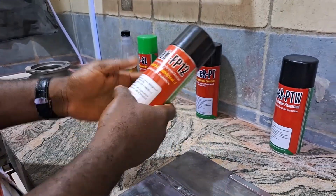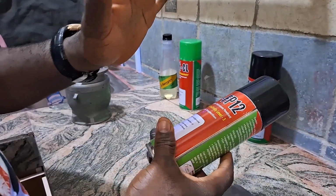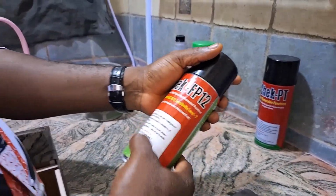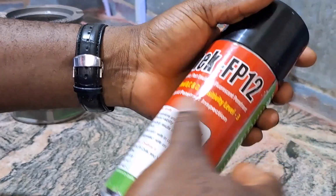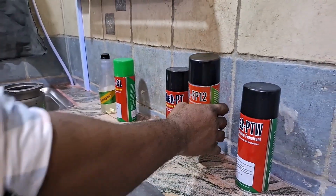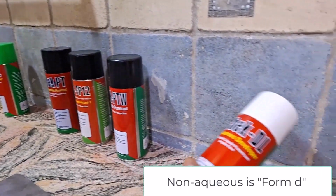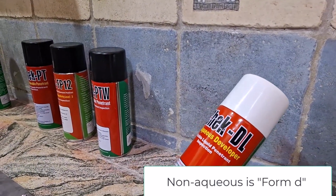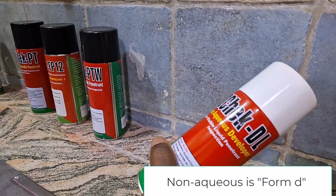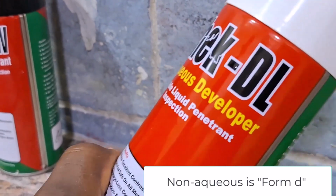So as an inspector, it's usually advisable that you take a look at what is written on your can while you are testing, to know the limitations of your testing kit. Then for this video, we are only going to be using the non-aqueous developer, which is from type C, for the development.